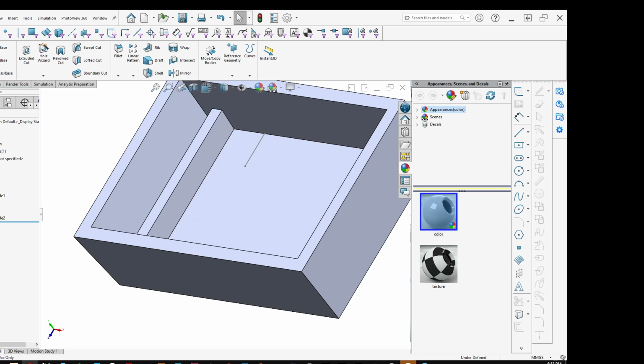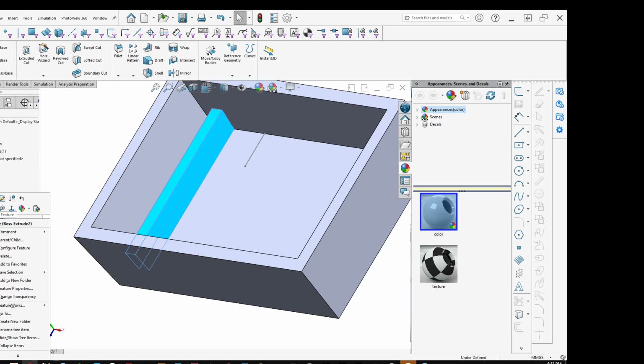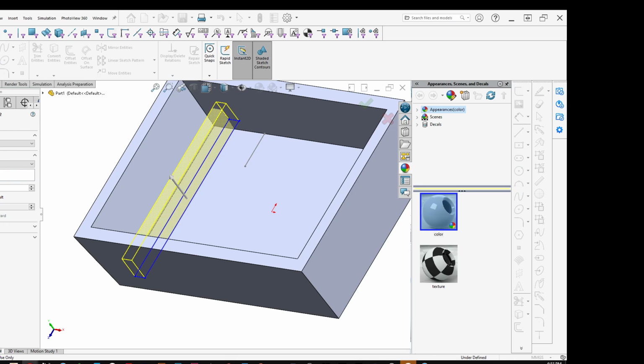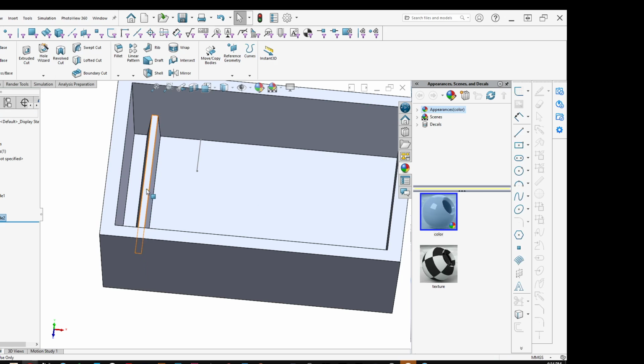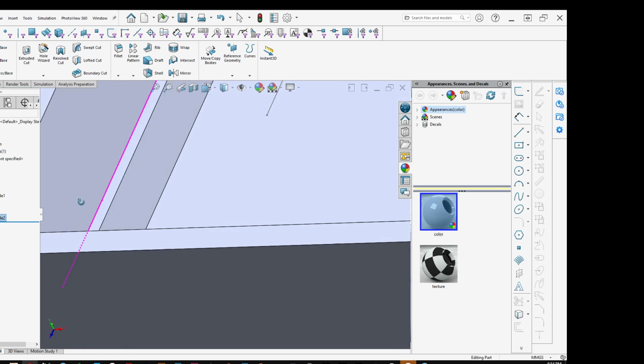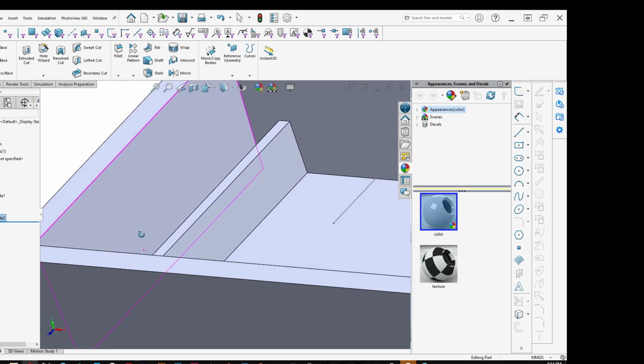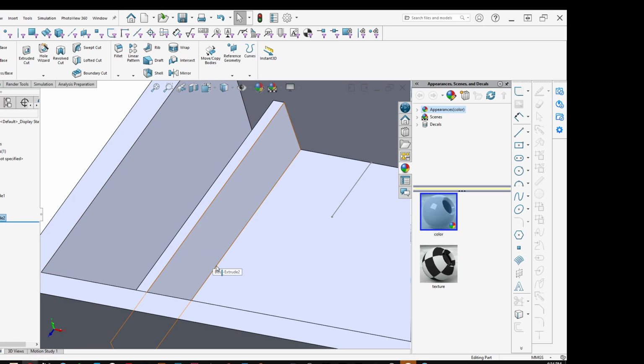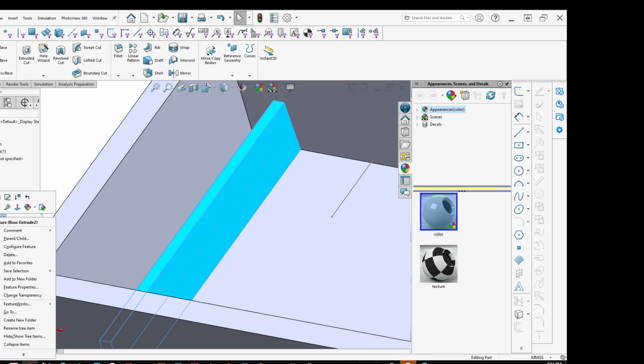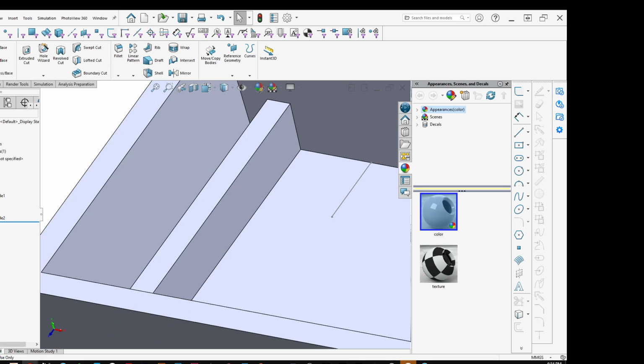I could have extruded it with the draft. We'll just do it exaggerated, so that you can see the drafts on both sides. Now you want to be careful, because if they say your wall thickness has to be the same thickness as everything else, what happens then is if you're too thin, it becomes really thin up here. So, but let's go back here, undo this.